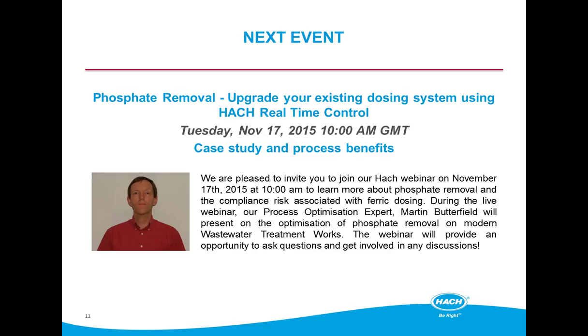Another question here, which relates to potential process enhancements. You mentioned that the given nitrification rate can be utilised better with the RTC. Therefore, would you expect an enhancement of the nitrification rate of a plant after installation of an RTC due to optimal growth conditions in the ASP? Yeah, you can. I mean, you're not going to change the fundamental biology of the plant, because that's simply what the controller does. It understands the kinetics of the growth rate or the ammonia uptake of the biology.